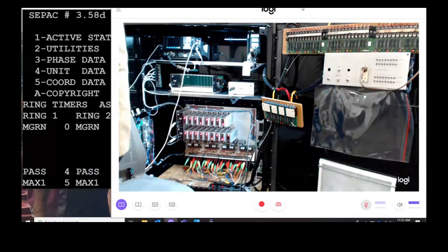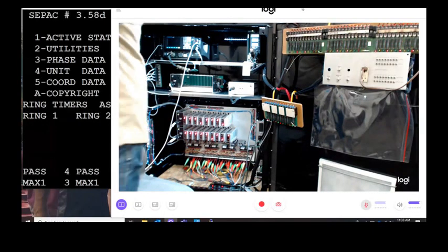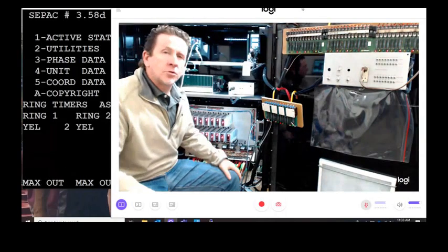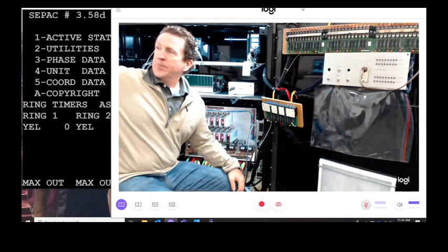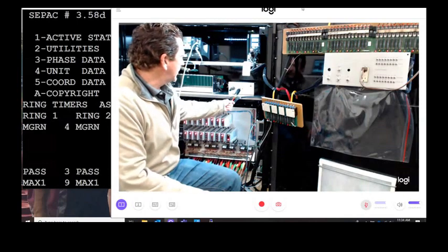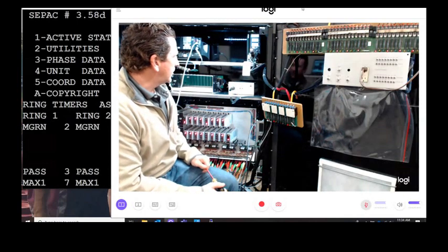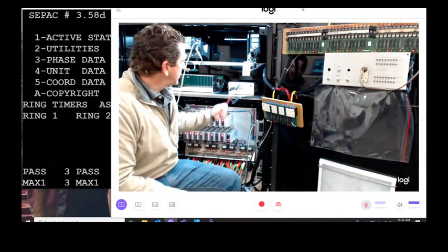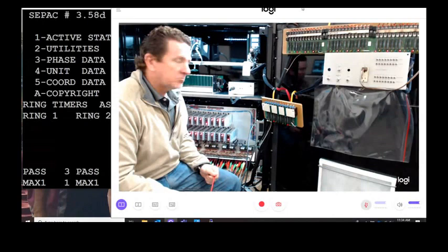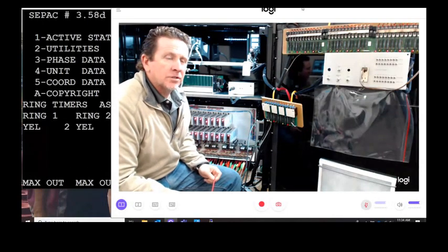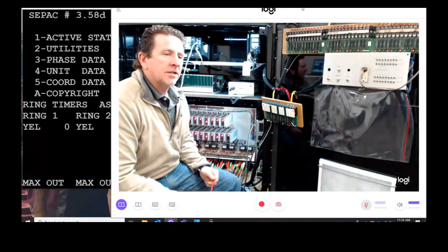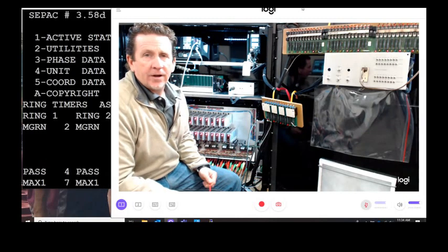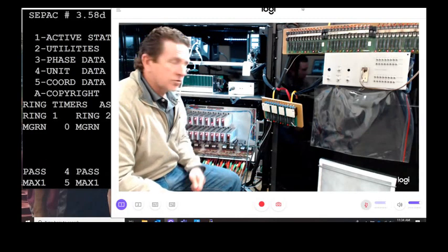All right. Okay, here's one while I'm talking about power supplies. This one throws people for a loop a little bit too. So on your power supply, I got my 12 volts DC and 12 volts AC, two auxiliary powers. We don't really use them that much. 24 volt DC, the main thing that we'll use it on is sometimes with some network gear that can run 12 volts to 35 volts, but most commonly we'll use it with GPS.